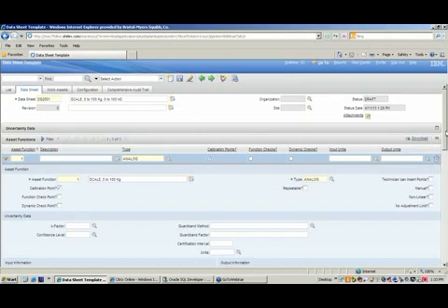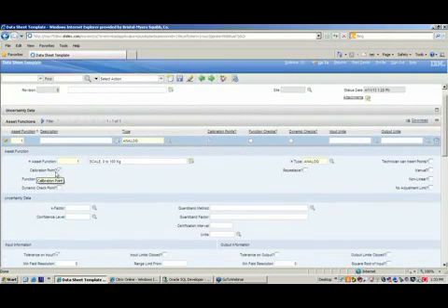So in our section, when we start defining it, there are other options. We're looking for a calibration point since it's an analog type device. We're not doing repeatable on this. If you need an option to weigh a particular scale multiple times, the repeatable function allows you to set this option and then enter the weight or value to be judged against, and for a repeatable value it will repeat that same value, and if by example set for 5, it'll repeat each calibration point that many times. So if we have one set at 10 kilograms, it'll repeat 5 times at 10 kilograms, allowing the technicians to do 5 separate entries as far as calibration points.